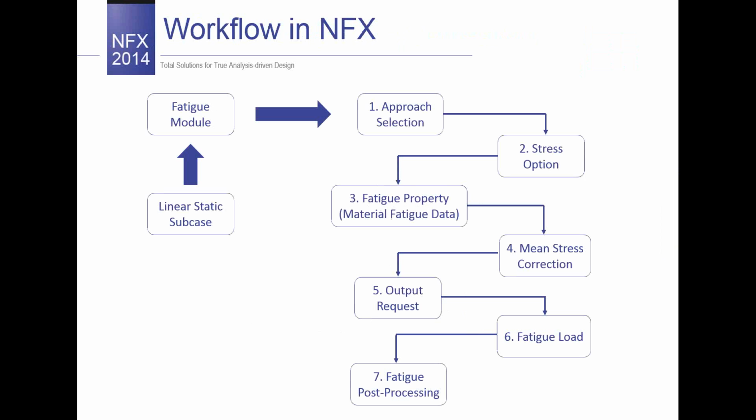So if you want to use the fatigue module, we're supposed to do this workflow. First of all, we're supposed to make a selection of the proper approach, so this is SN method or EN method. After that, we have to select the proper stress option, select or provide the material fatigue data, set up the mean stress correction, set up the output request. We have to assign the fatigue load, and after that, we are able to get